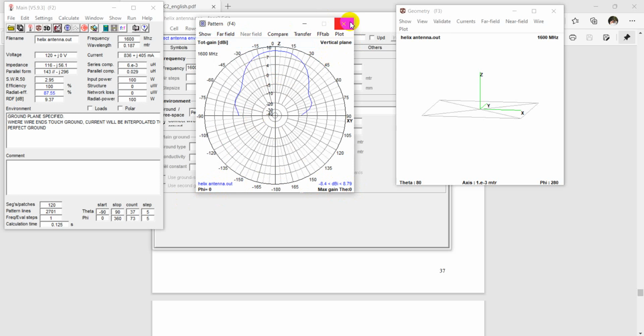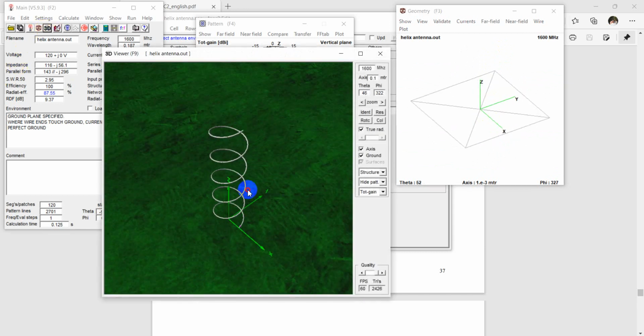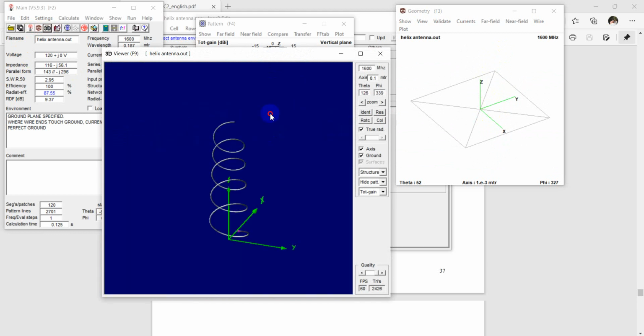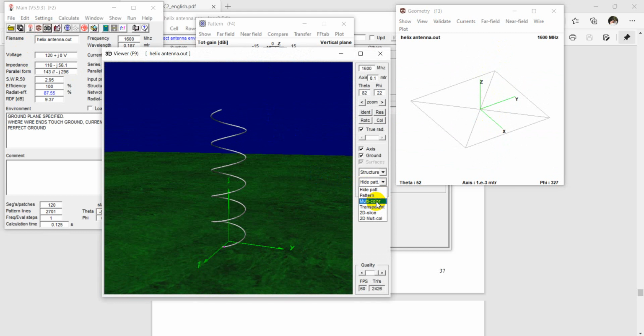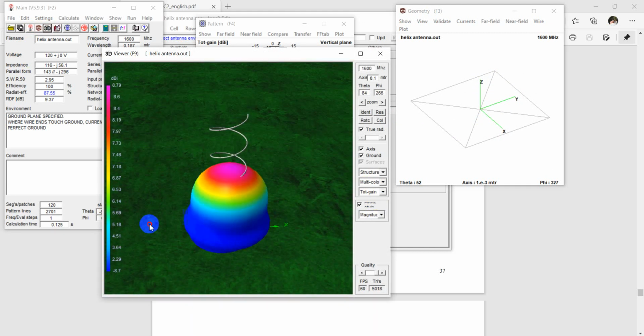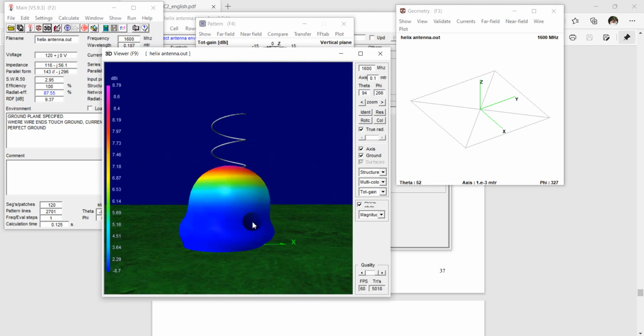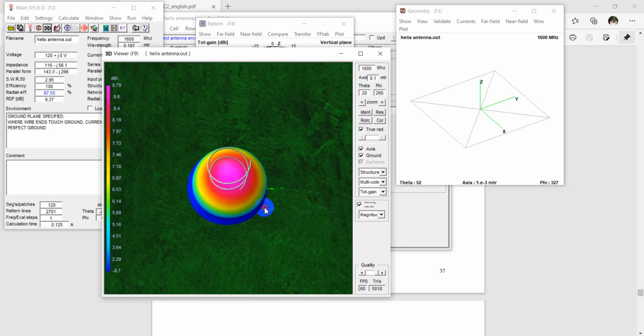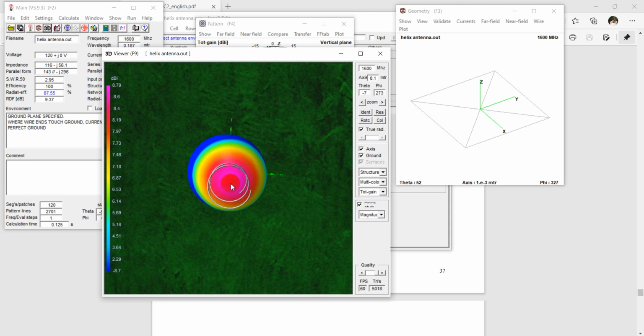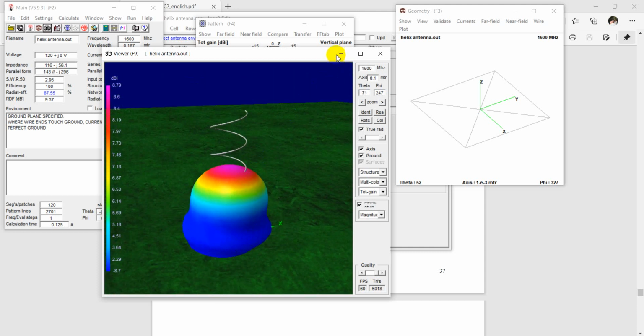After seeing that, the design is ready, but the parameter is so high that the antenna is not showing here. To show this antenna, we open the 3D window and generate this parameter. When we show the multicolor pattern, the radiation is shown in the blue portion, which indicates that the radiation is nil at this ground side. When you go to the top side of this antenna, you can see the violet portion, which indicates that the maximum radiation happens in this part.